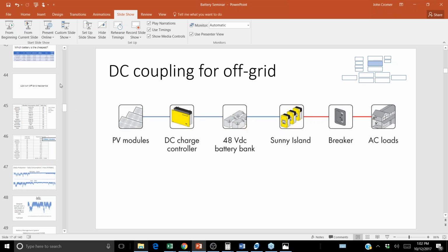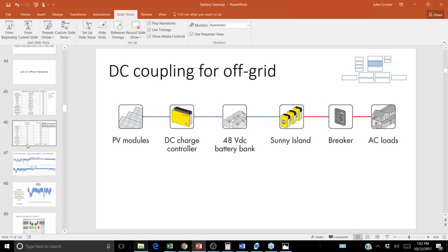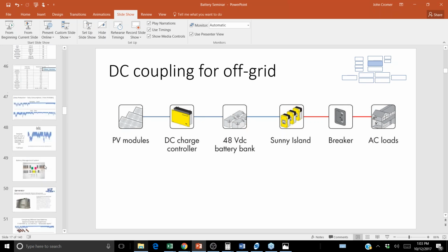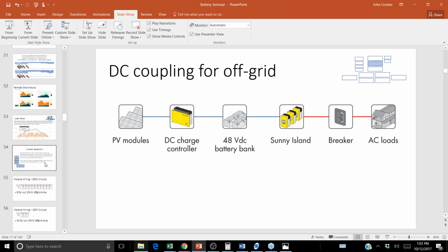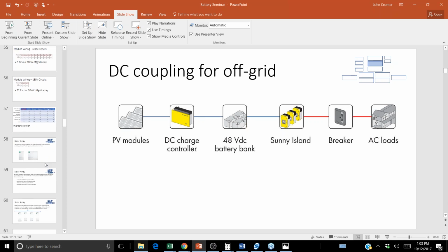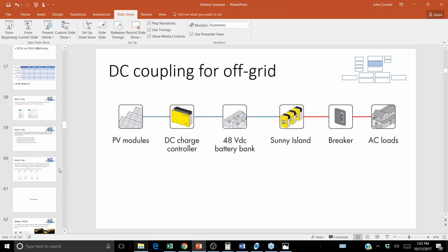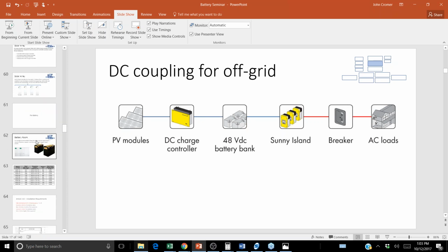When you do a charge controller, you have a DC panel. A little bit more complicated, a little bit less upfront cost. Again, you're really only dealing with DC charge controllers when you get into residential off-grid. Otherwise, you're staying AC coupled, where you have the solar array on its own inverter and the battery bank on its own inverter, at which point there's no DC to DC connection into the battery, at which point you don't need a charge controller.